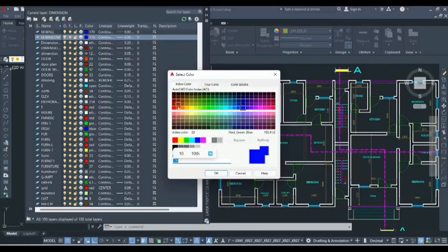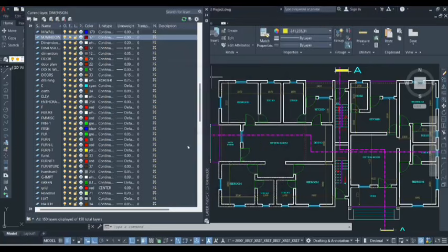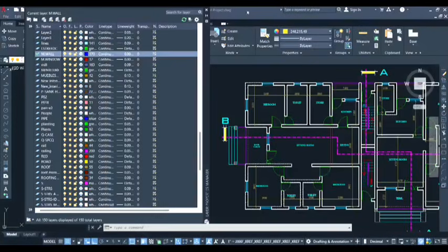Now the color, change the color to red and change to whatever color that suits the specification. Since we are dealing with window, we are going to leave it to continuous line and the line type to be 0. So now we've created the layer for wall. I denoted it with M dot wall. We've created the layer for window, M dot window, to differentiate it from the existing walls and existing window on this drawing. So you can create more, just follow the same step.